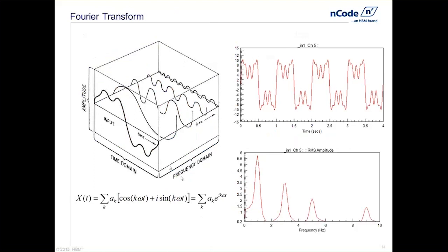If we look at this 3rd dimension, however, the frequency domain, we could take this very simplified signal and perhaps represent that with a few sine waves. And in this case, we have 4 sine waves. Each one of these sine waves has an increasingly higher frequency as we go along this axis. And you can see that the amplitudes of those are also unique.